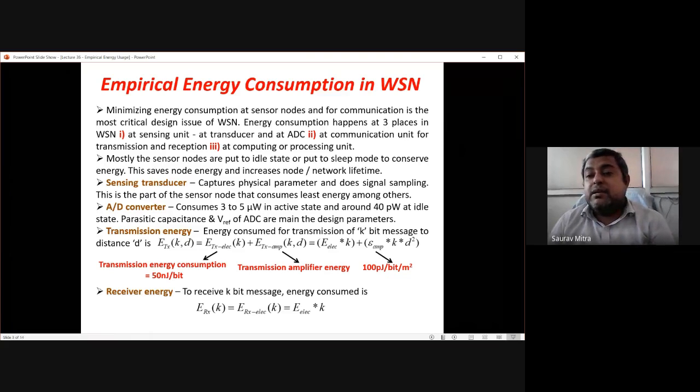Okay, so when the communication distances are more, the transmission and receiving power requirement will be more. If some sensor node is not only sensing but also processing, taking some decision, and sending the data back to the sink node, then more than sensing, it is doing other processing-related jobs, and the computing and processing unit will require more power. So first you have to understand which are the main works that the sensor node is doing.